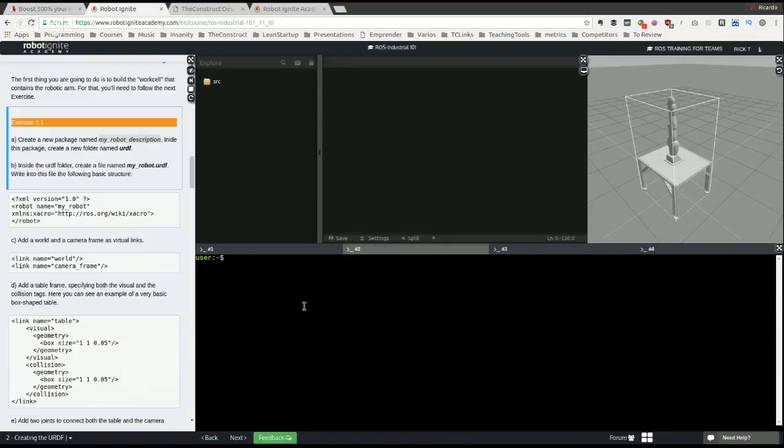And I'm going to create a package. For that, remember, always, you have to create your packages inside the Catkin workspace /source. Okay, so if you see here, we have a Catkin workspace directory, and there we have to go to the Catkin workspace. Then here we have the devel, build, and source. We have to go to the source, and there is where we can create our packages. At present, we have nothing, of course, because we have just started. So let's create a package.